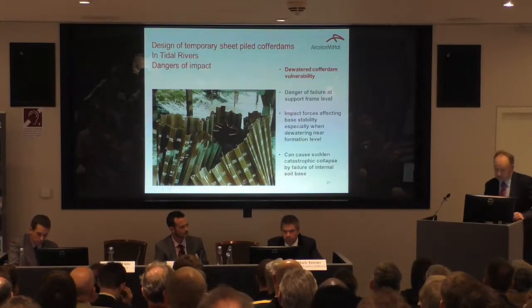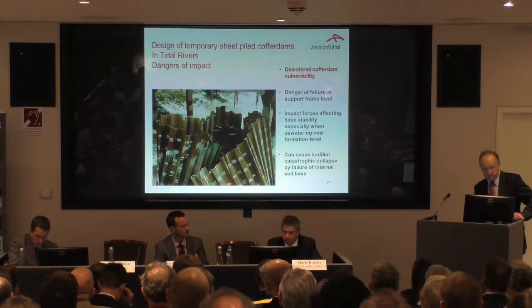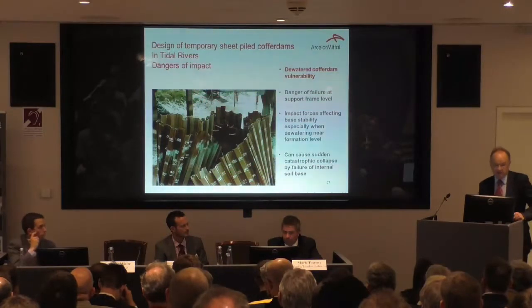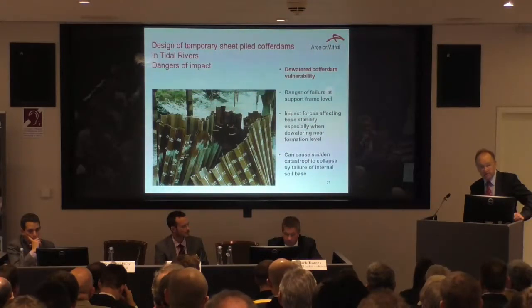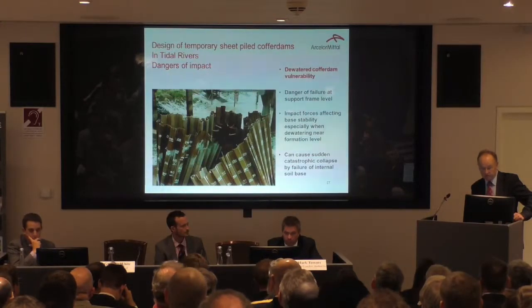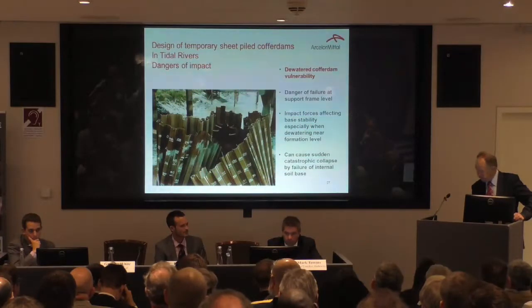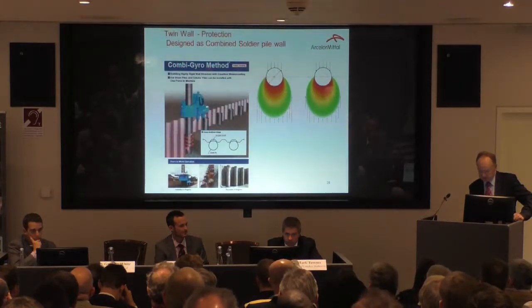It's certainly a lesson to be learned, and when a vessel hits a temporary structure, it can easily disturb the formation at the base level, and in soft soils exacerbated by water pressure and piping, you can lose the whole base. It'll pop out through the bottom and the structure collapses. So it's something certainly to be wary of for designing structures against vessel impact.